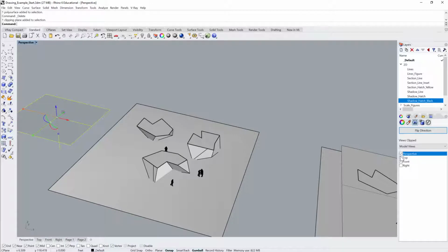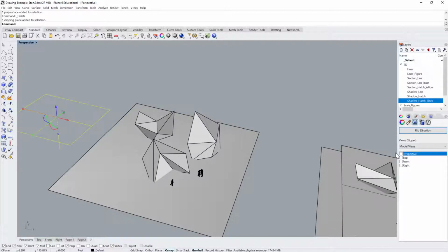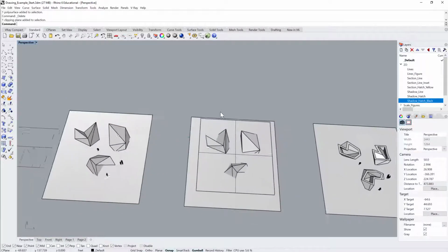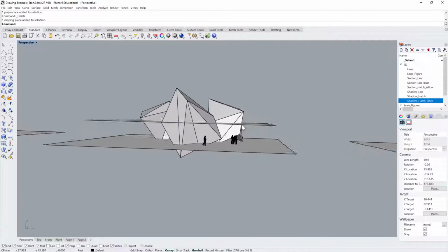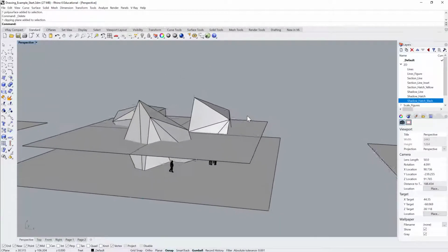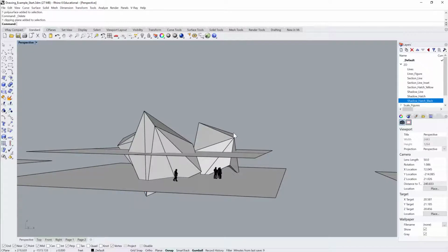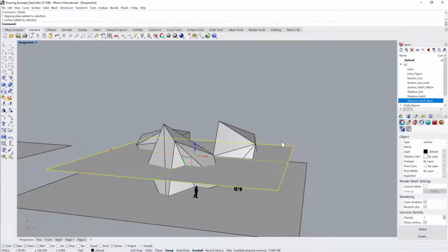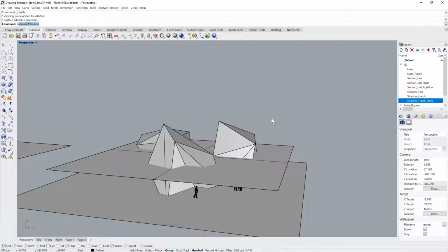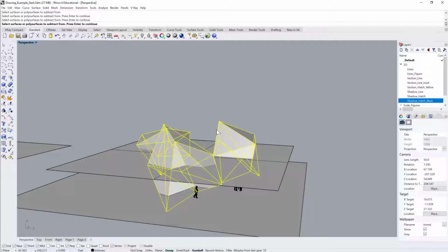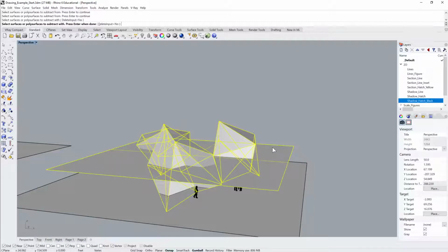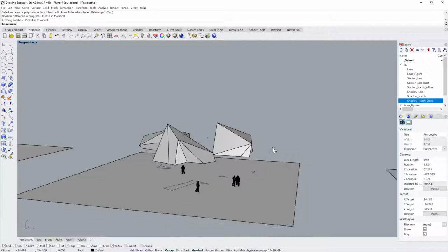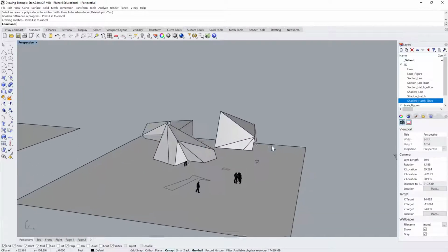So I just deleted that offset interior shell. And what I've done is I've copied those objects over here. And I'm basically just going to trim away what I don't need using a Boolean command. So I'm going to type Boolean difference. That's actually just what popped up. Hit enter. I'm going to subtract from these surfaces. Enter. Subtract with this. And it actually isn't subtracting what I want.